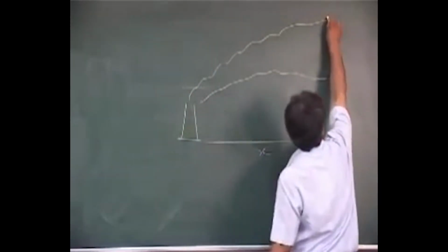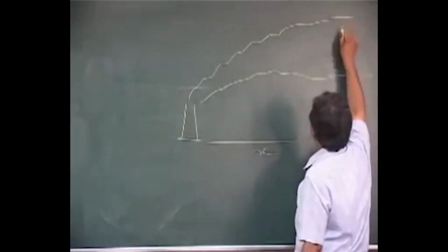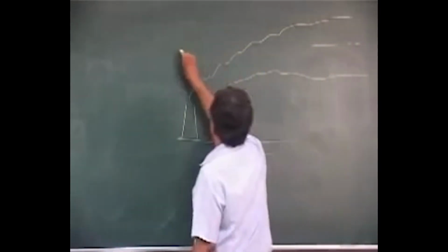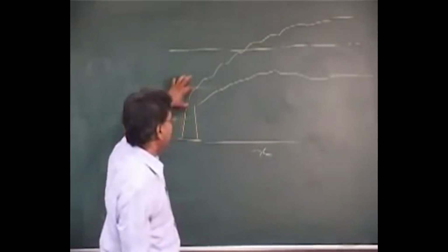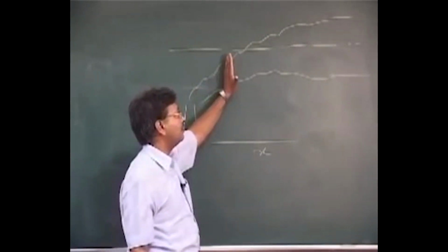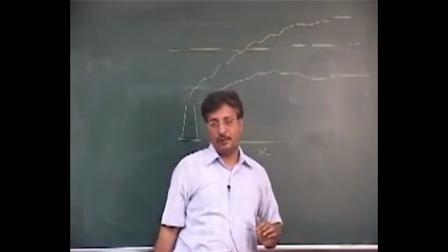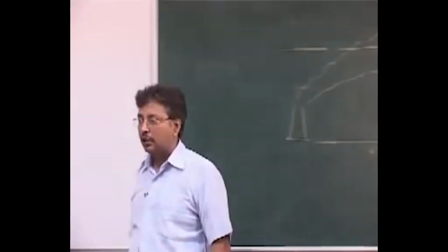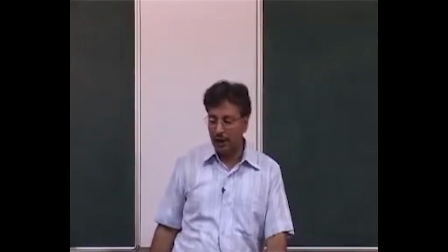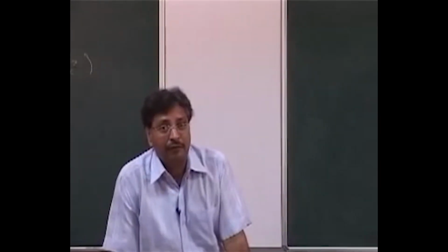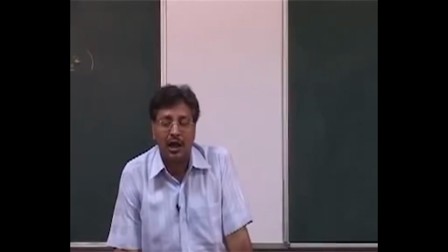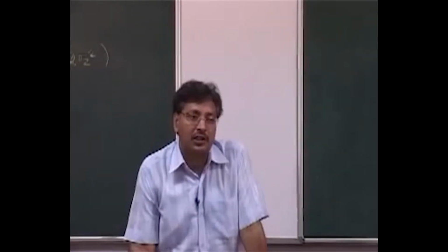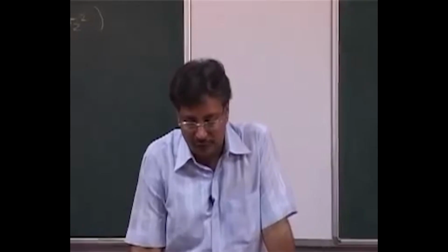Only after a certain distance of x does the h stabilize. Here h is different at each point. So some people who want to do things very precisely would take even h as a function of x. In more sophisticated models, this is taken as a function of x. But for simplicity, we may not really do this.